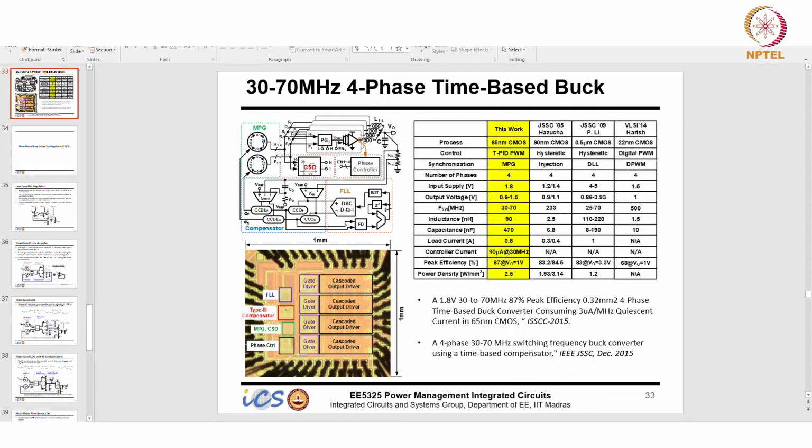But the VCO is running at 4x, so it will have some extra current obviously. But if you compare this extra current from running the VCO at 4x with the complexity and the current you require to generate for the current balancing and all those, that is much simpler here. Because current sense itself is not simple to do.